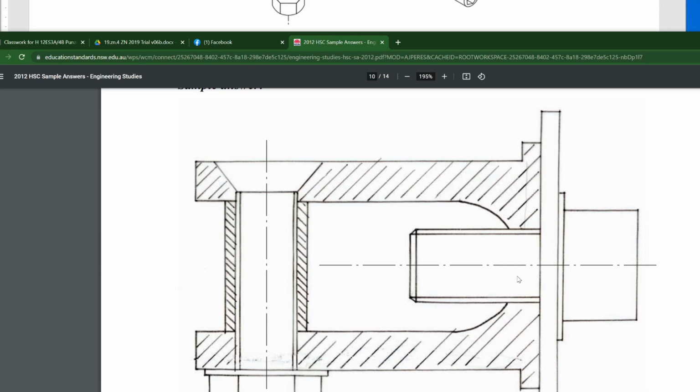because it just wants you to understand that you don't section washers, that you'll lose marks for not showing bolts. Now, the thing I'll point out here is that there really should be a difference between your line weights. So I should be able to tell a difference between your thick dark lines and your thin dark section lines. And I can't see that in this diagram. So that's something that I would point out.